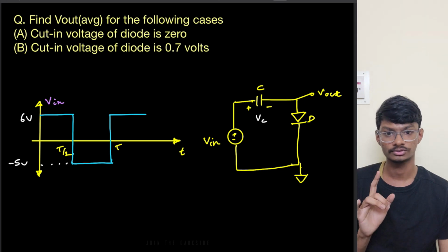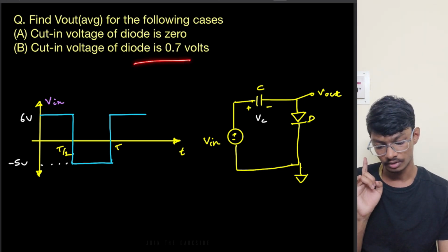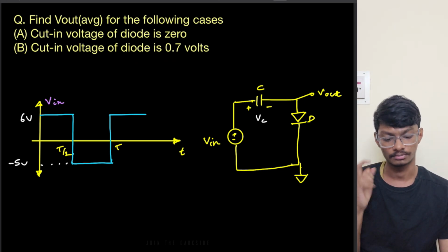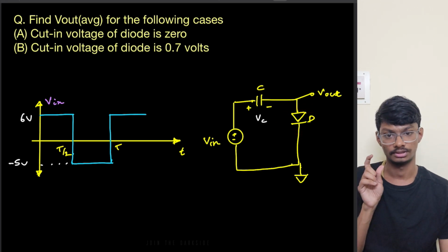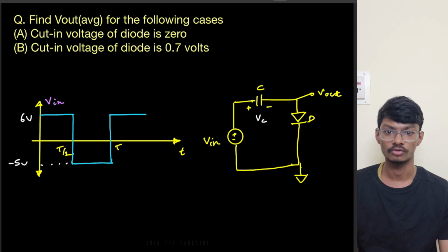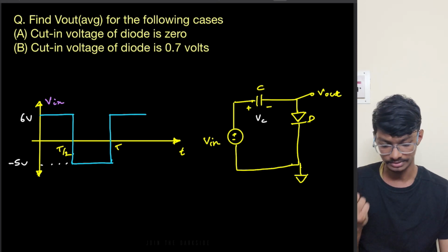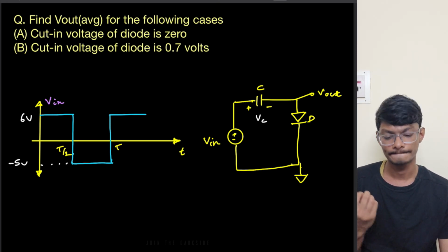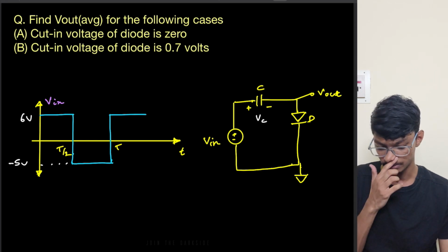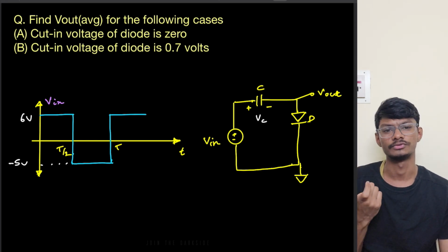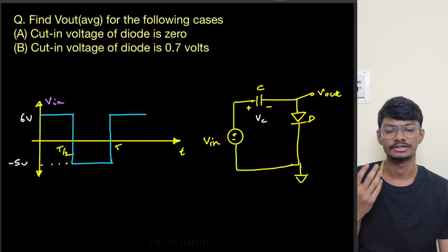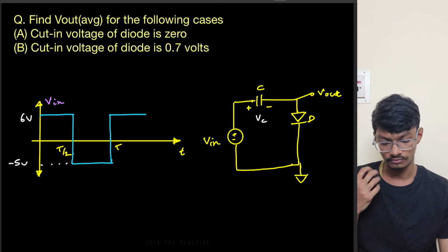Now what I will give you as homework is to solve it when this diode has a linear piecewise model. Basically this diode has an on resistance also. Solve for that case. Take the on resistance as 1 ohm and the capacitor as 1 farad. And solve for when the time period is 5 seconds or something. Then solve for the question.